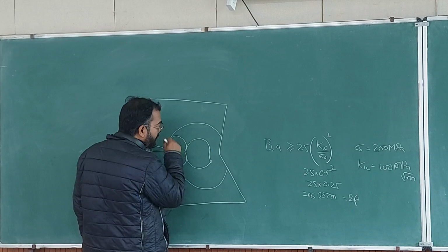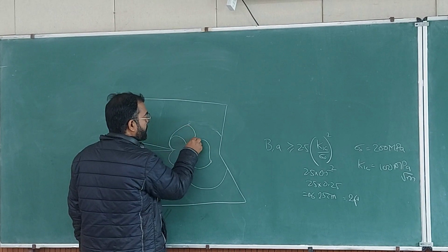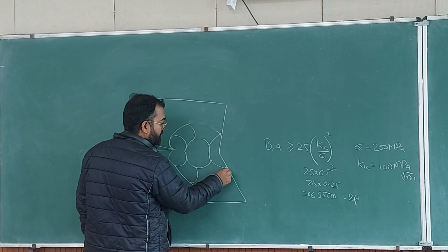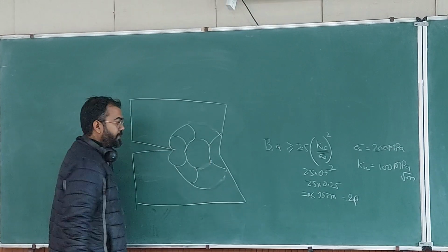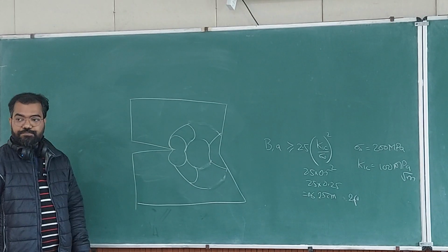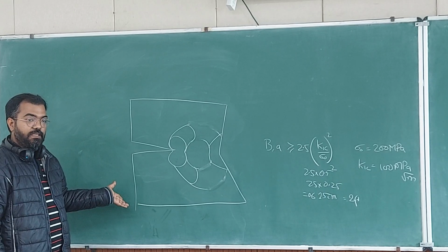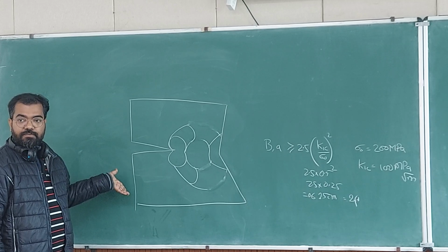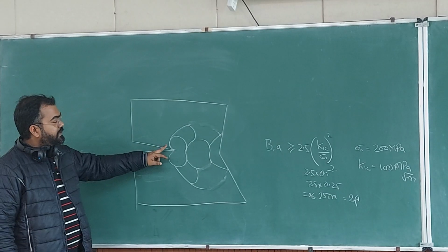plasticity everywhere, and then you will not be able to make out that which zone. So before this stage you will have something like this, and here we'll have back face plasticity. Okay, so the area at the back side is also deforming plastically, but there the strains are compressive. Okay, and when crack moves, it moves.